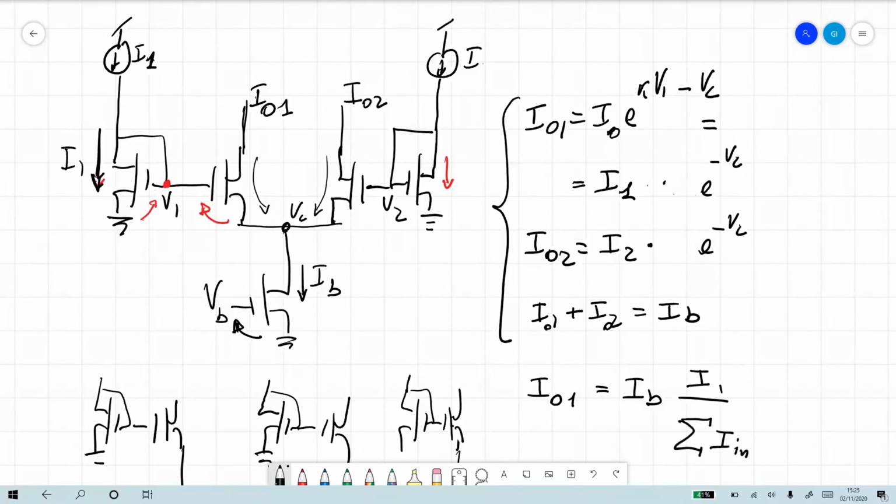Okay, so after all of these corrections, now it should be correct. I trust that you can actually solve it yourself. I was just going quickly, but it's good that you're catching all of these mistakes. But as I said, we didn't make any assumptions for kappa. If you remember to normalize by UT, everything should be okay. And in the end, the nice thing about these current mode circuits is that the output current, you can express it as a function of the input current. And you can even scale it by IB.